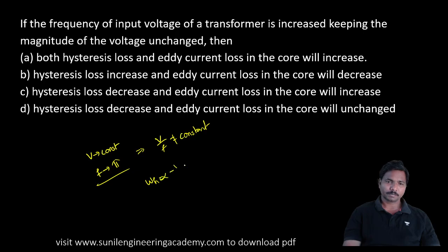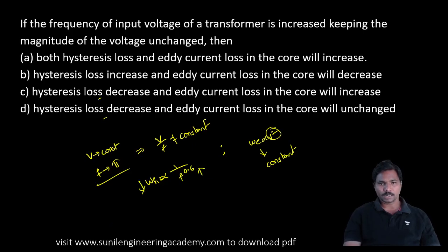Generally inversely proportional to F to the power 0.6 now, and eddy current loss is proportional to V square. So V is constant here, so eddy current losses will be constant. As frequency increases, hysteresis losses will decrease. So hysteresis losses are decreased and eddy current losses will be unchanged. So the answer is option D.